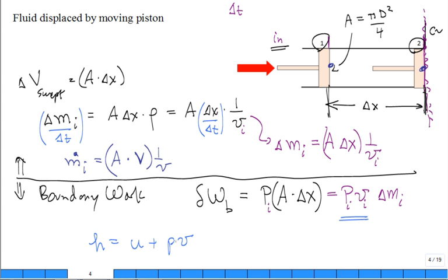How do we ever get that PV term? This is the way you do it. I'm driving it right now. So that PV term would be like a flow work term. That's why they would describe it. The flow is coming into the control volume, and it's the boundary work pushing it into the control volume. Now there's going to be some flow work coming out. It'll be the opposite direction on the outlet pipe. Okay.